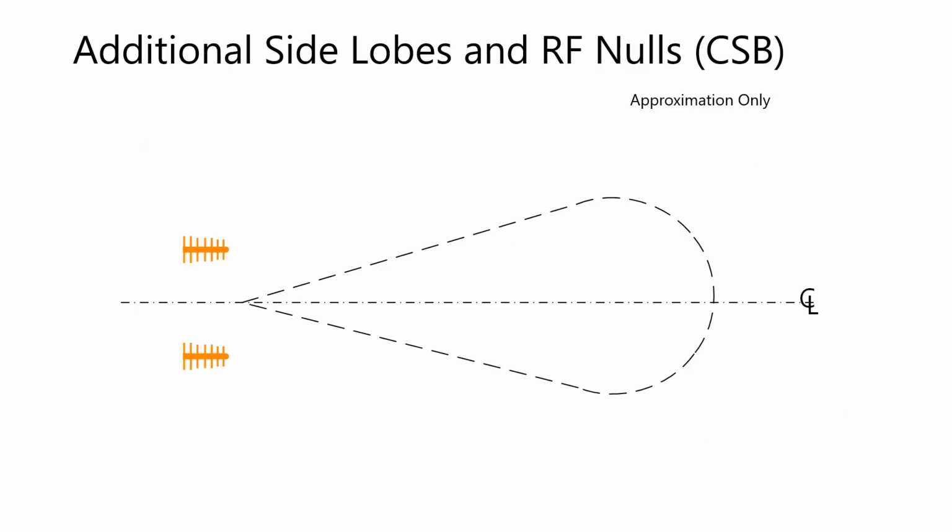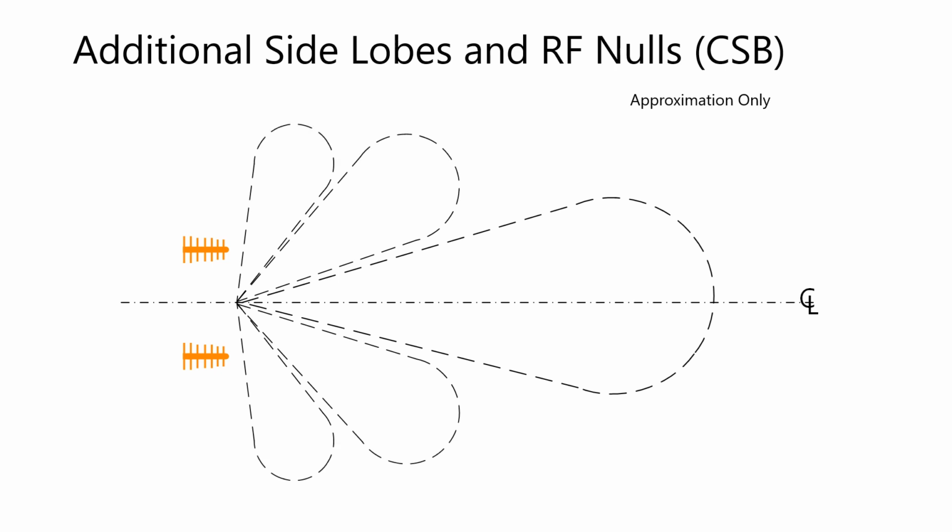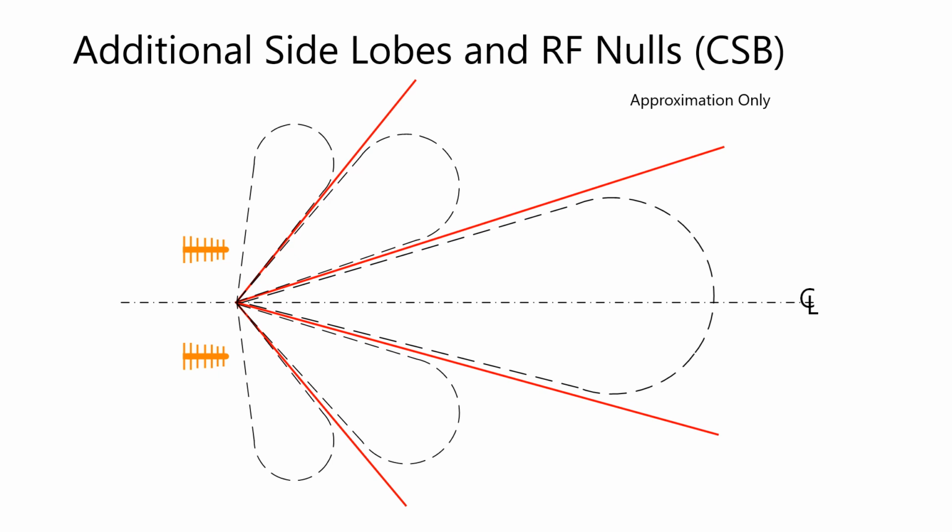An important fact of RF pattern development is the unavoidable creation of additional lobes. Between these lobes are nulls where the signal drops. Different techniques are used in the distribution network to develop the main lobe to be broad, thereby reducing the signal strength of these side lobes. However, this may not be practical due to adjacent local reflections such as buildings or taxiing aircraft.